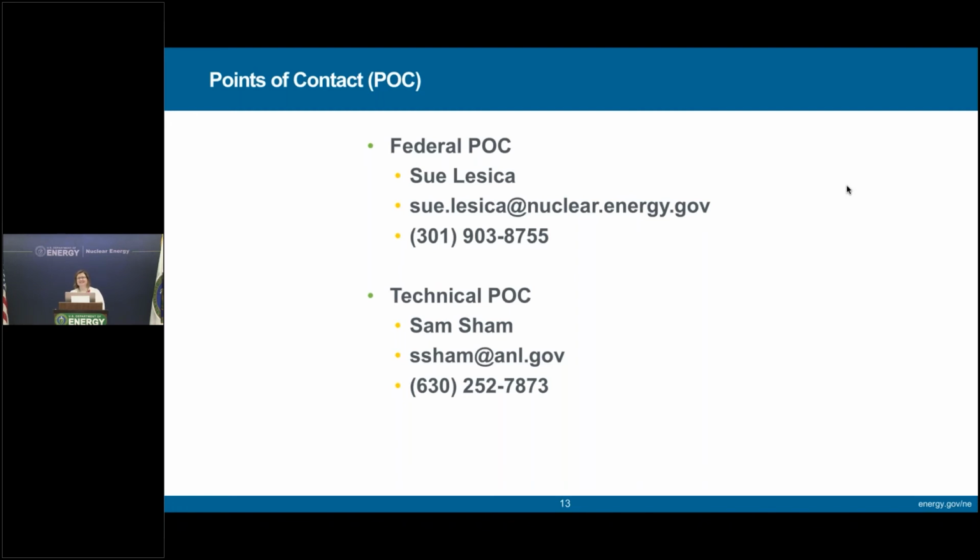Okay. Why are ceramic materials excluded from the work scope? Because of our ability to only fund a few of the proposals, we're focusing on metallics at this point. In the future, we may focus on different areas, but that's our focus right now. Yeah, and also we're looking at structural materials, structural component applications. Ceramics will have a lot of the good attributes that we are looking for, but it brings in other issues in terms of fabricability and joining. A ceramic component cannot be placed in a reactor all by itself. It has to link to other components, which could be metal. So that's the reason why we want to focus more on metal for this time.